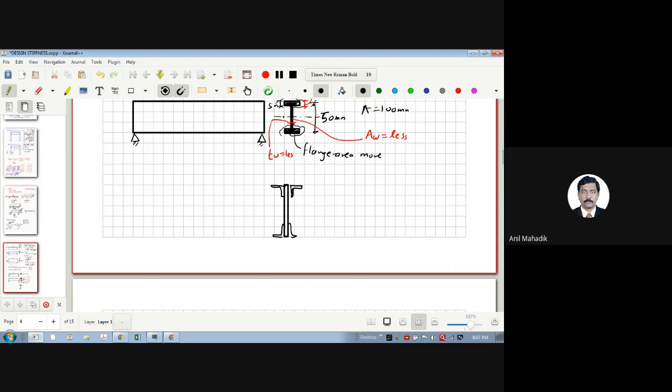So you can see the depth is more here, and I have more mass here. I am adding angles at this point, and the mass is away from the neutral axis, which means the depth is more. So this way also we can make sections in steel structures.